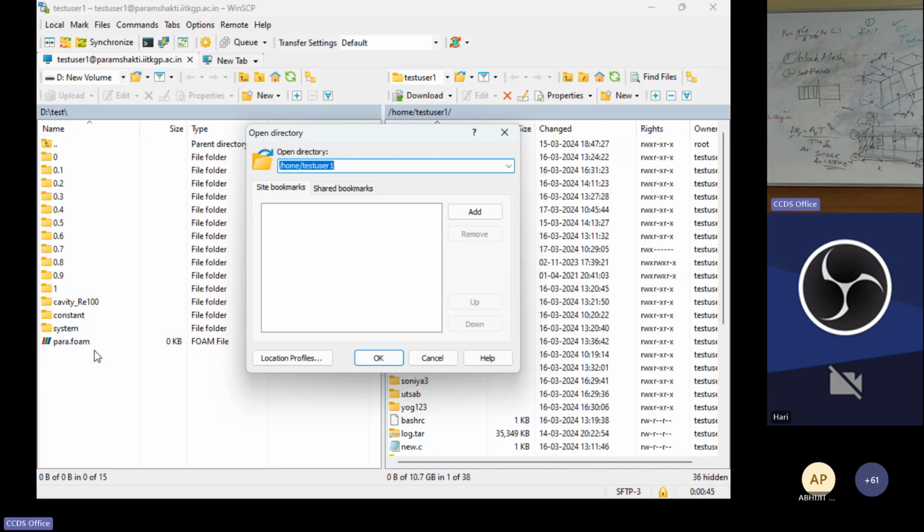That's what I was telling earlier. In the controlDict file, you need to make that adjustableRunTime. In the controlDict file, that entry, if you can open that, go inside system. cd system. Where are you right now? Go cd system, vi controlDict. Open it. All right. Inside there, write controlDict adjustable. Instead of that adjustable, write adjustableRunTime.